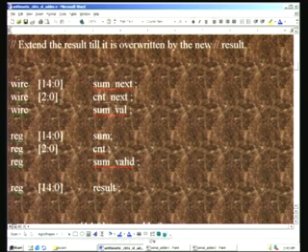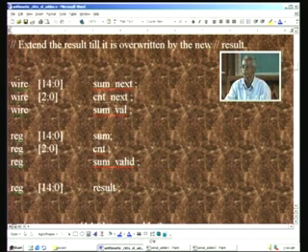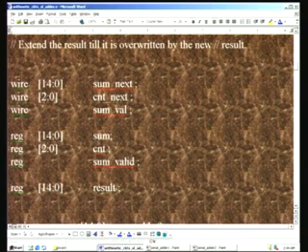We also have to keep track of the number of inputs that we have already processed. For example, we are inputting only n0, and then we need to update a counter, and it will go from 0, 1, 2, 3 and so on up to 7, and therefore we need 3 bits here in order that we may keep track of the number of inputs that we feed here. In this particular design it is n0 through n7, which is actually 8 numbers, and therefore 3 bits are adequate.